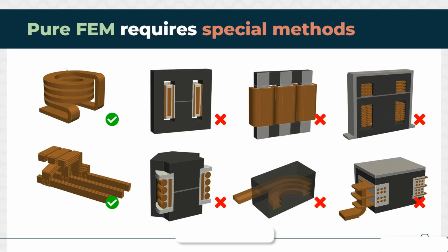So as you can see, with the FEM formulation in its pure form, we would only be able to solve very simple conducting problems, maybe also simple cores with magnetic fluxes in the core, but we would just be able to apply voltage, because in the AV formulation we apply vector potentials and scalar voltages. So all we could do here is apply the voltage from the terminals and calculate the currents and magnetic fluxes resulting from that. But no current excitations, no circuit connections, no litz wire, no foil windings.